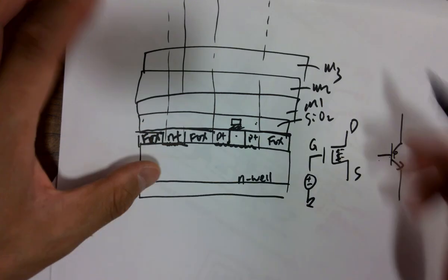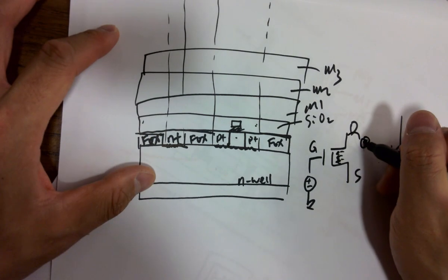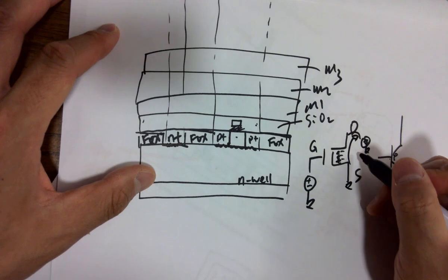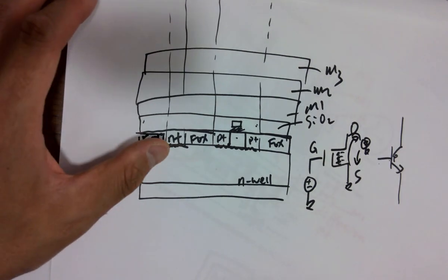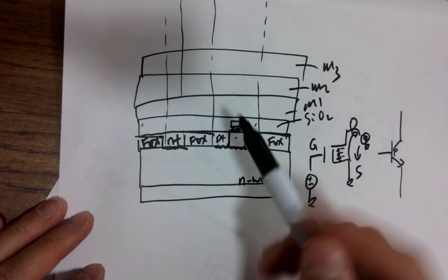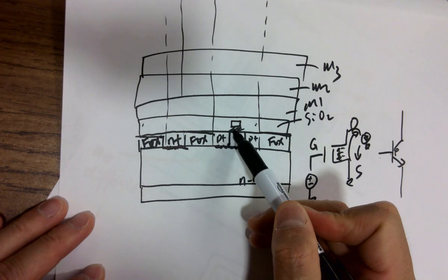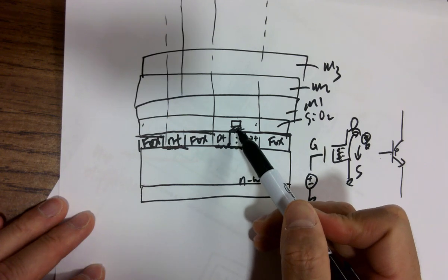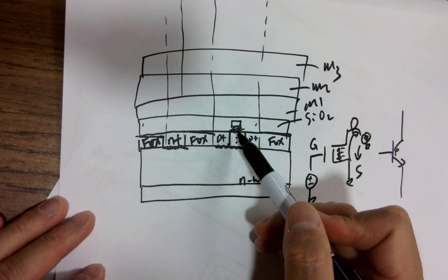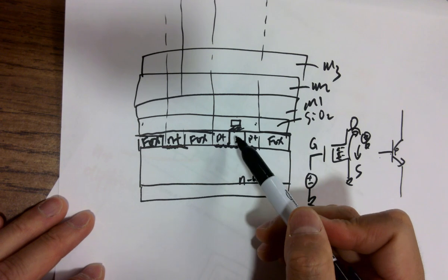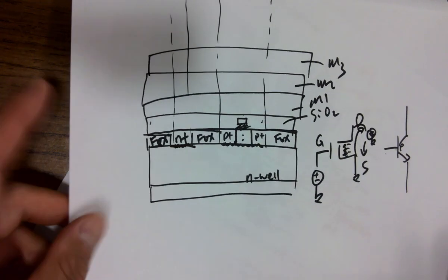That's how that works. And then you apply a potential drop at the drain, and the electrons start flowing that way, and the current starts flowing that way. That's how it works, like a switch. But you have to form that channel first by the electric field. So the gate is not making a direct contact with the channel because you want to create the electric field instead of injecting direct current into it. We don't want to inject current into or take current out of the channel. Make sense?